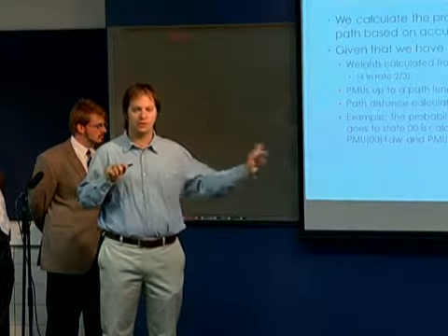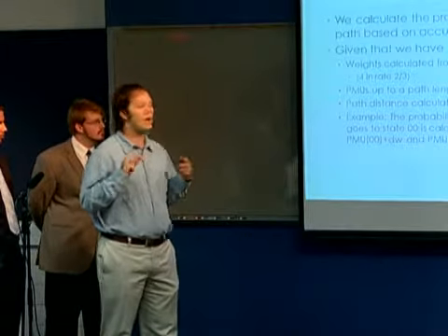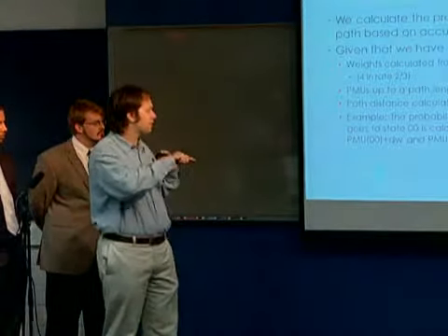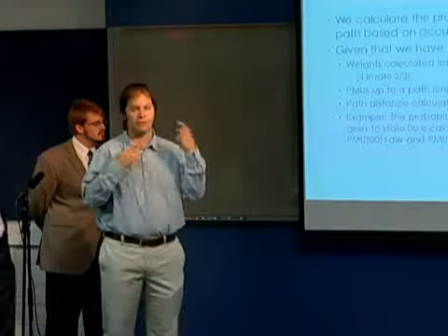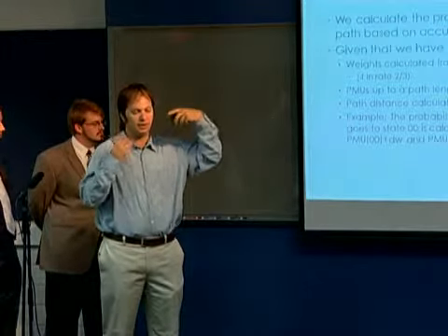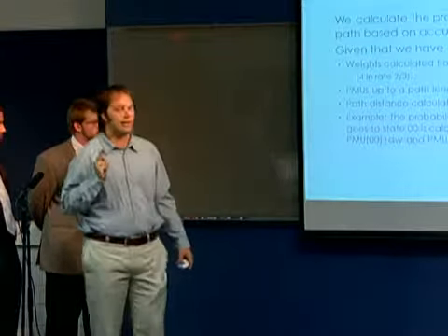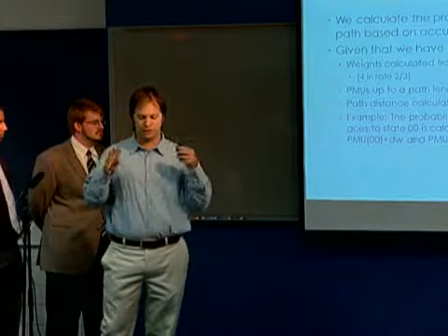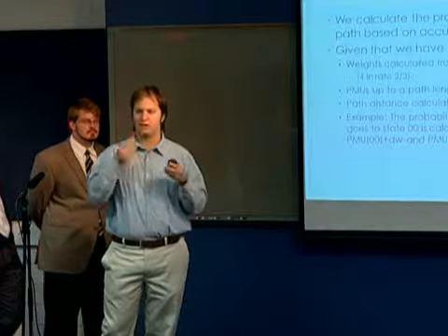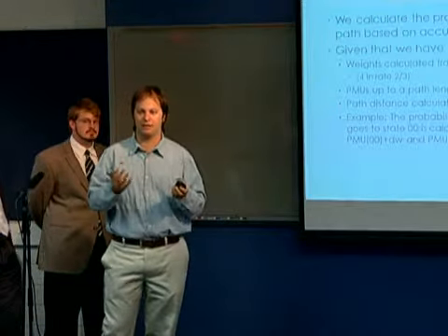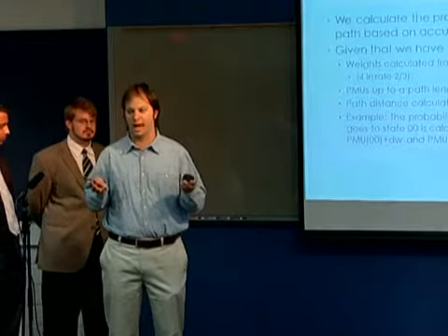The minimum of those 2 possibilities is going to be our weight for state 00 at our current point, using the weights from the previous points. The minimum of those 2 is the most probable path to that state. And we do that for each state because we want to keep all the minimum possible paths. So essentially we have 4 minimum possible paths at any given point. For our rate 2/3, it's going to be 8 possible paths.